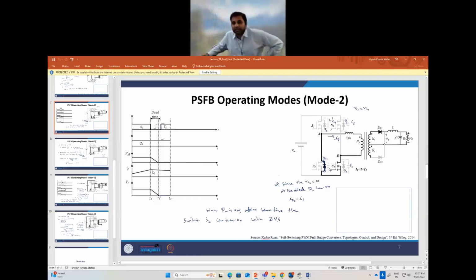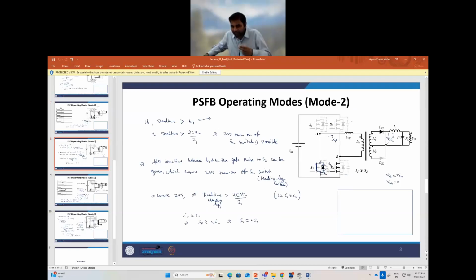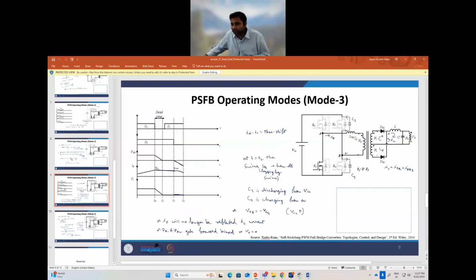So now what happens is that this current is falling. Now the moment you give the negative voltage across VAB, what will happen? This current is still there, which has to be maintained from this point, but on the input side you have applied the negative voltage. Because of the negative voltage, it will try to force the current to have a negative slope on the input IP, and that is when this current will no longer be equal to this current.